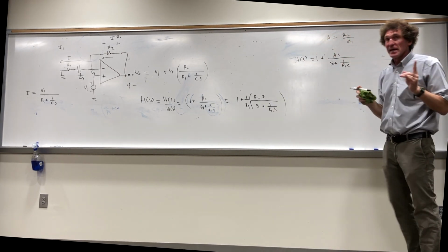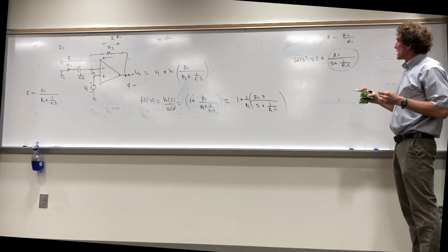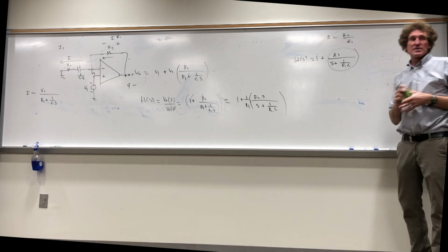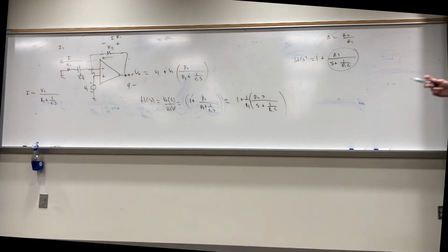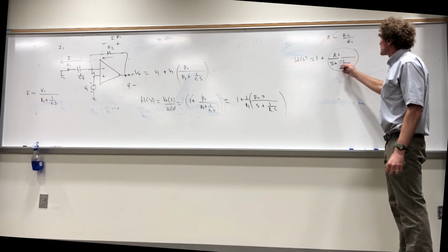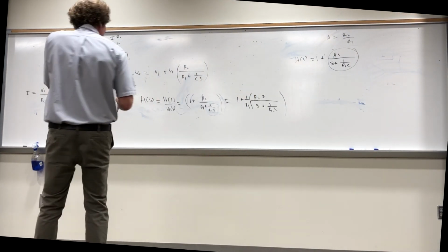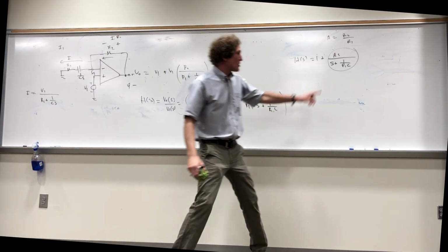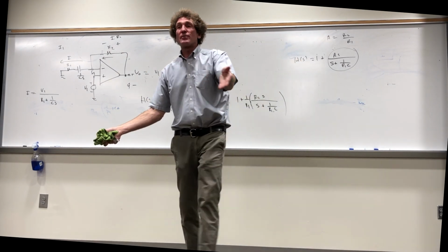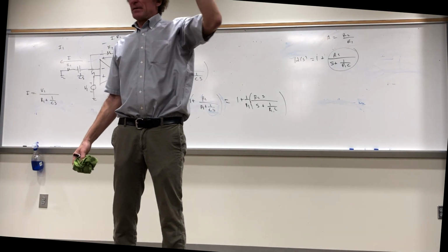Actually, I don't need to expand that anymore. I can get a single denominator if I want, but this will work too. What does 1 go back to in the time domain? Delta t, right? Now what about this one? What is 1 over S plus, call it A? It's e to the minus 1 over R1 C times t, right? But if there's an S in front of it, that's the derivative with respect to time, correct, class? How many see that? I am out of time, but I'm trying to make sure.